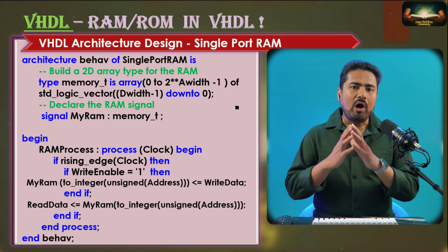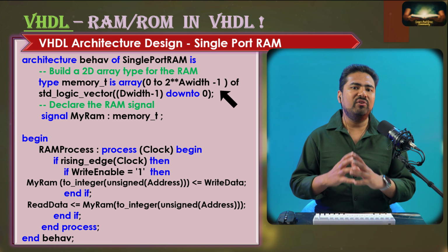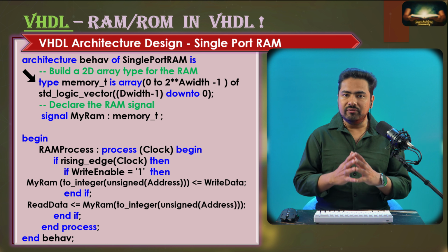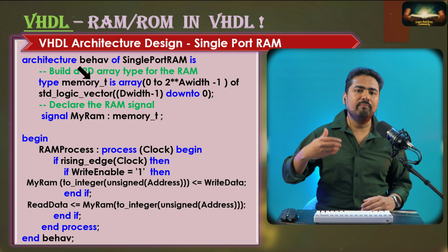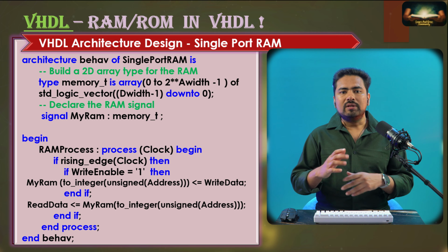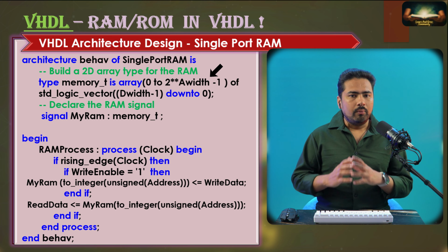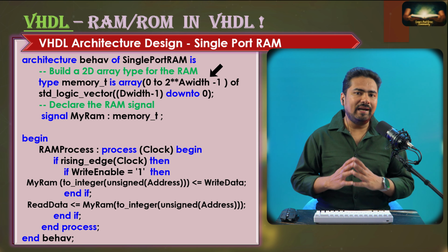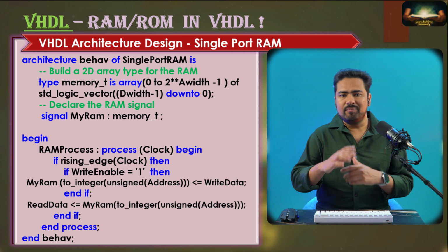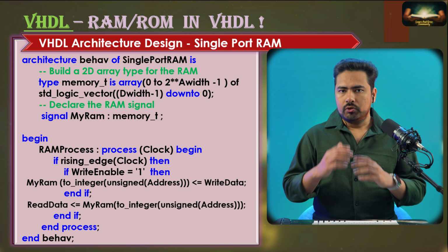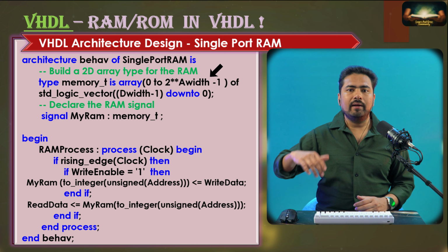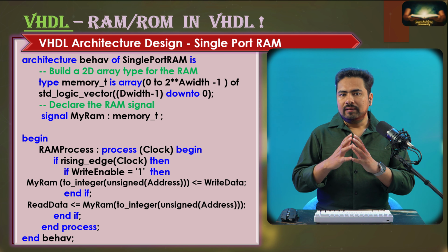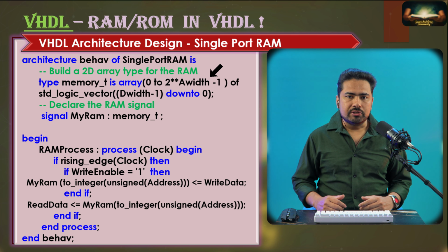We already know how to create a custom data type in VHDL. So we used the keyword type to create our custom data type named memory_t. Now the size may confuse you a little because we have used generic parameters here instead of some hard-coded inputs. So our length has the range from 0 to 2 to the power A_WIDTH minus 1. This tells your memory locations.